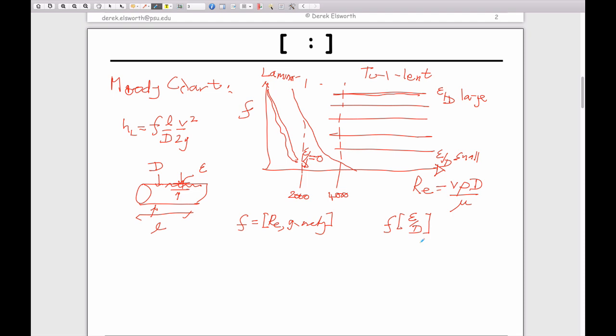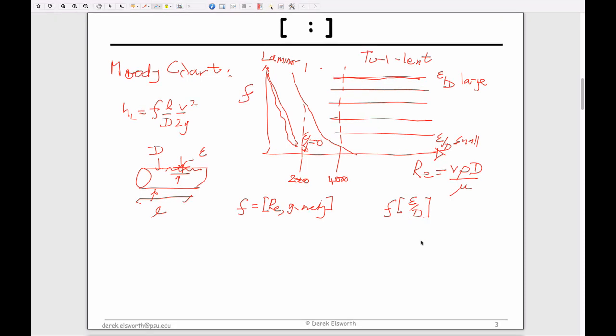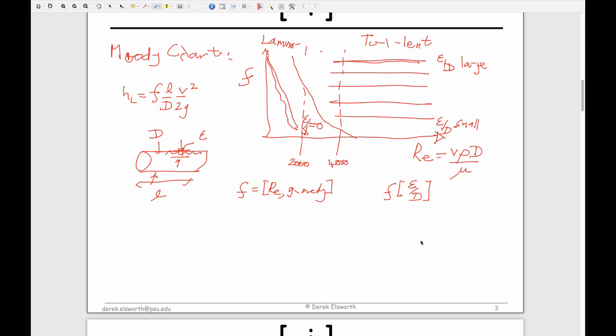So that's pipe flow and how Moody charts fit into that, a badly drawn Moody chart in that. And so the only other part, which we've actually used to explain pipe flow as well, is dimensional analysis. So we developed the Moody chart equations kind of from dimensional analysis, which of course is one way to develop them. And I suppose that the three cardinal components of dimensional analysis are the ones that we perhaps alluded to before.